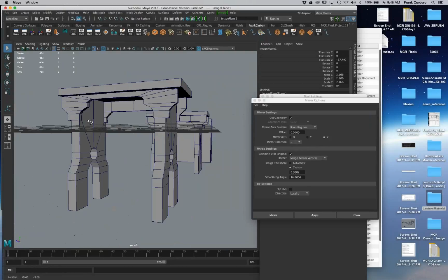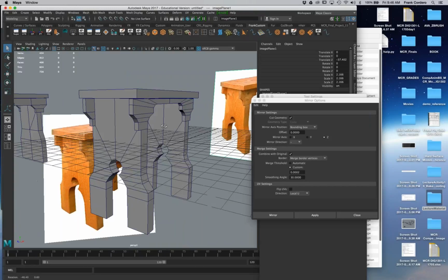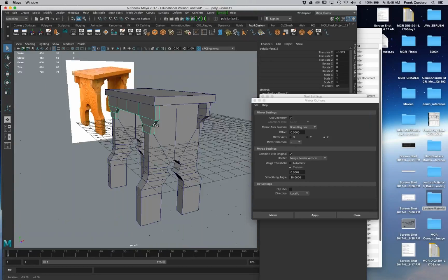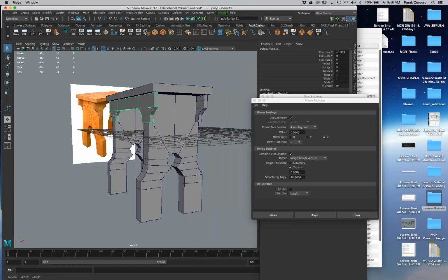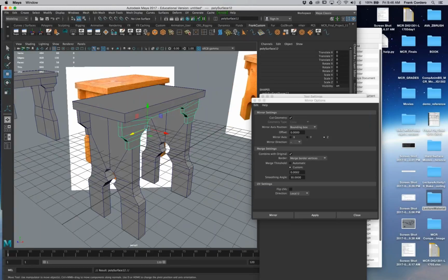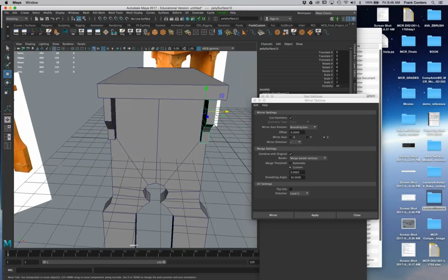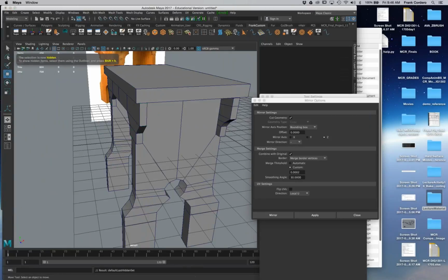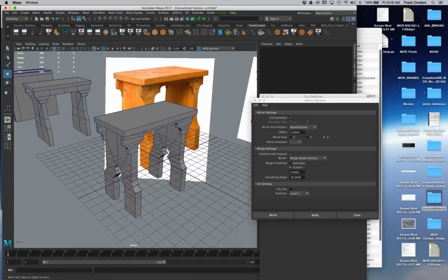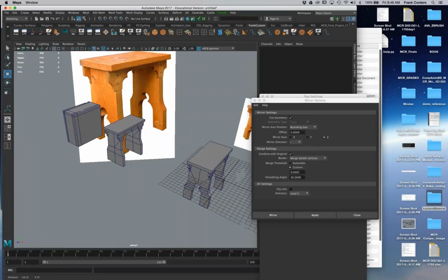All right. Now, resolution-wise, we could definitely add more edges. But it's definitely good right now in its current state. And guess what? We're going to use the position of this. And I'm just going to go ahead and cut and paste this command, duplicate. All right. And hold down the V key. Snap it in place. Control H. Get rid of this guy. And then Control Shift H, bring back the other one. All right. So this is where we are so far.